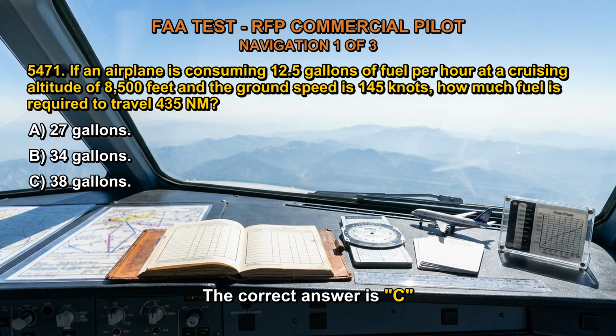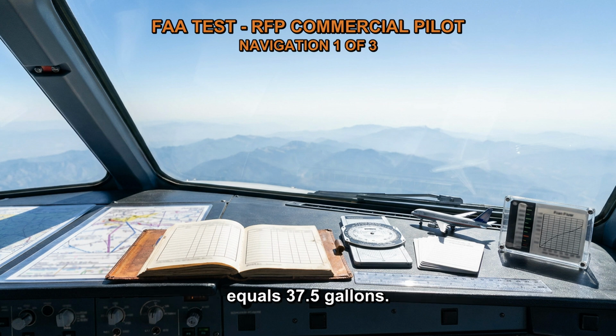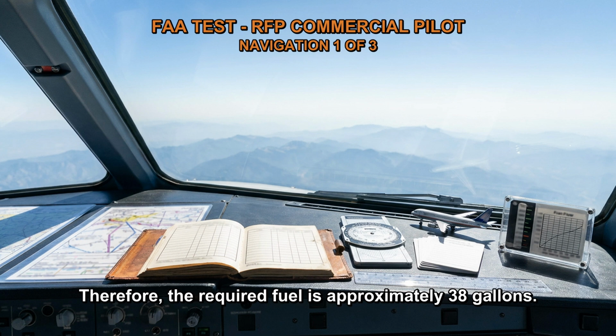The correct answer is C. Determine the travel time as follows. 435 nm divided by 145 knots equals 3 hours. Quantify fuel burn. 3 hours at 12.5 GPH equals 37.5 gallons. Therefore, the required fuel is approximately 38 gallons.